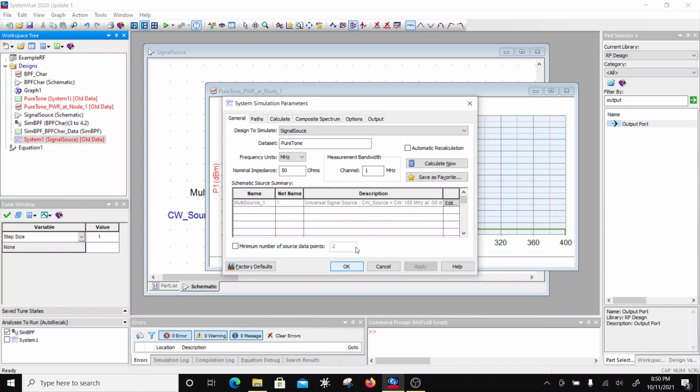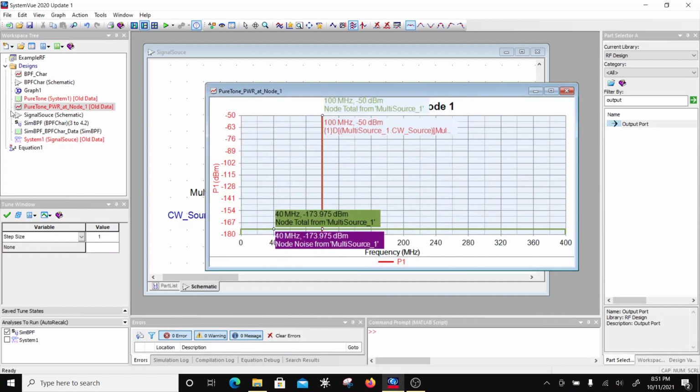That is your total system bandwidth, so you may be integrating noise over the entire system bandwidth. Or in this case, if I was to put the channels and then look at that, because I will have filtering once the down conversion takes place, the channel bandwidth would be put here rather than the system bandwidth. Okay, so this is for the noise integration.